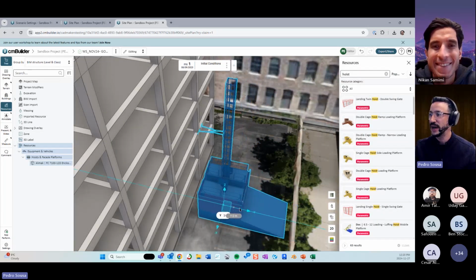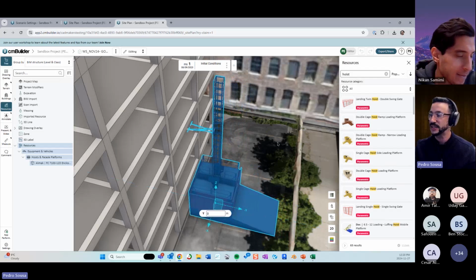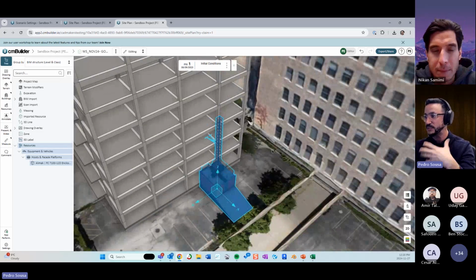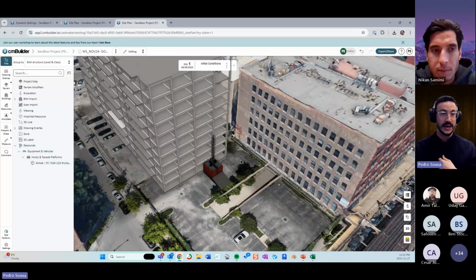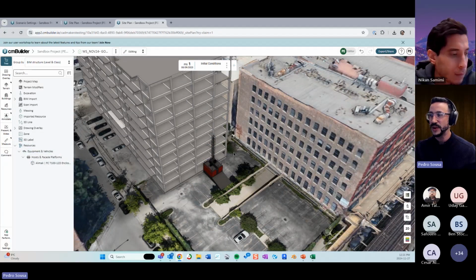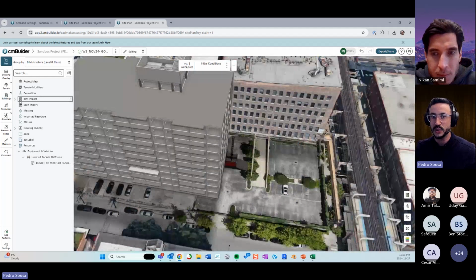Anyways, so basically this is how you do it, right? So you can now define this project north, because it will make your life much easier whenever you're drawing things and so on, especially when you're using your sketch tool, right?